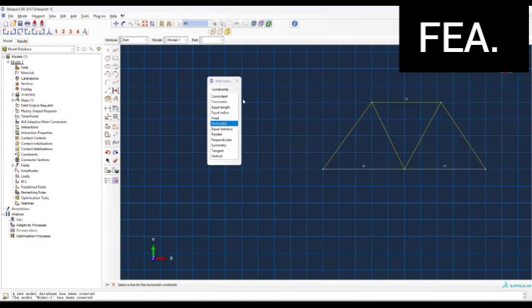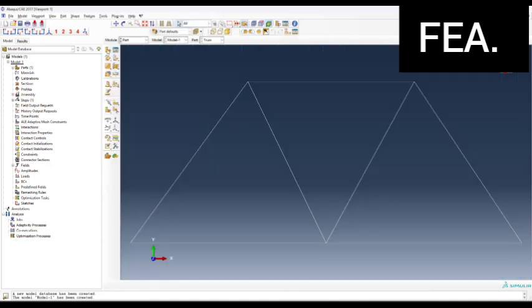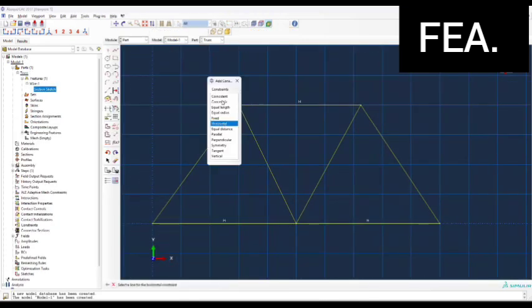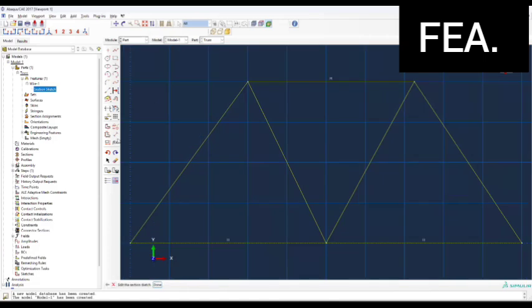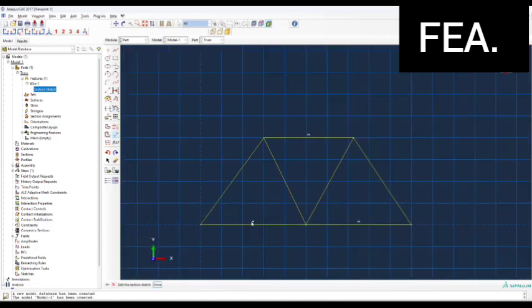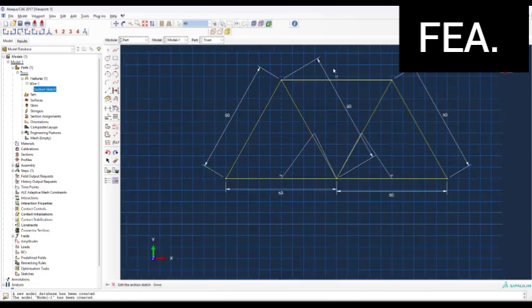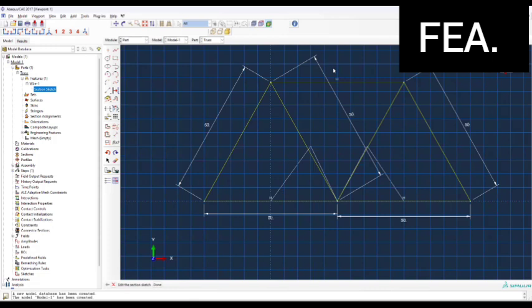These two horizontal. Oops, sorry, go back into the part. Okay, so horizontal, this one. All right, so now we can prescribe lengths. If I define this one, it'll become over-defined, as you can see right here. It'll turn pink. But I could just undo that, and then it's going to be adequately defined. If you put too many constraints, it's a problem.